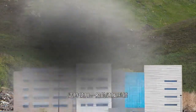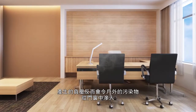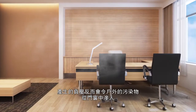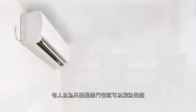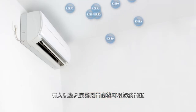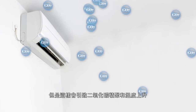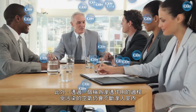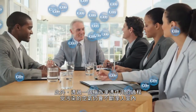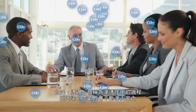When outdoor air is not suitable to breathe, negative pressure will only make indoor air worse, as outdoor pollutants will seep in through the windows and doors with the airflow generated. Some people might think that staying in an airtight room will solve the problem, but this will allow the buildup of carbon dioxide and temperature, and will actually do more harm than good to the people inside. Moreover, polluted air will also continuously seep into the room through a process called infiltration.